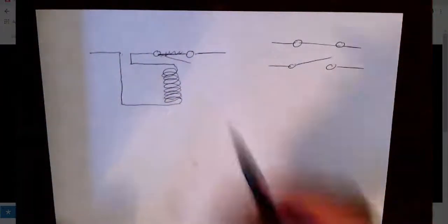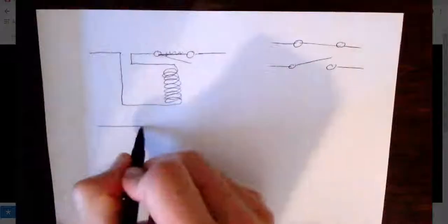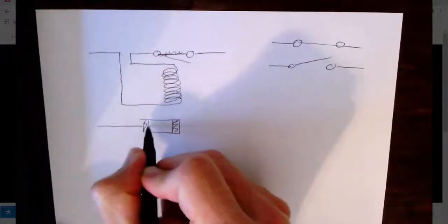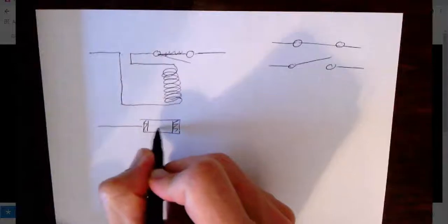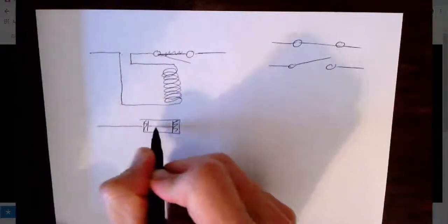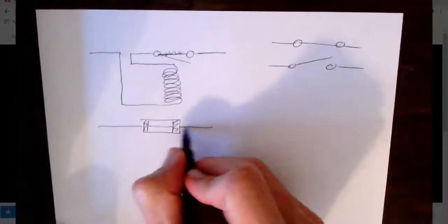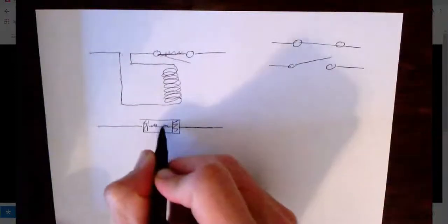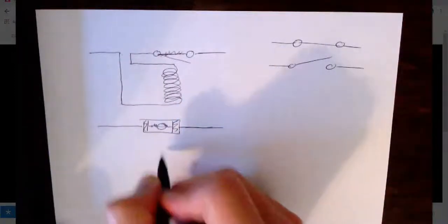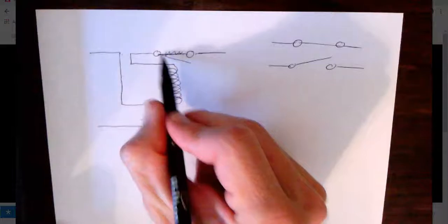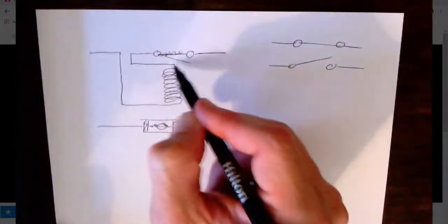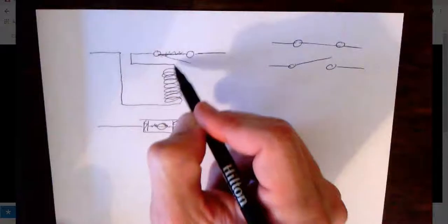So remember we talked about fuses. Fuses are much more simple. They just kind of look like this. This is a piece of metal and a piece of metal, and then inside there is a thin wire. And if the current through there ever gets big enough, this thing burns up, and there's a gap, and the electricity can't flow. A circuit breaker opens a switch, and some of them use an electromagnet, a solenoid, to open that switch when this current gets too big.